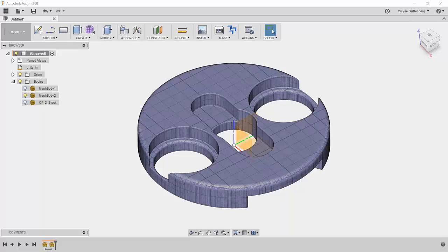Yeah, it comes back to those facets again. If you're making an STL, sometimes they let you set a level of accuracy, and more accuracy isn't always better because it means more facets. And if it's a fairly simple part and you have a lot of facets, you're creating a huge data set that you may not need. Yeah, that's a good point too.